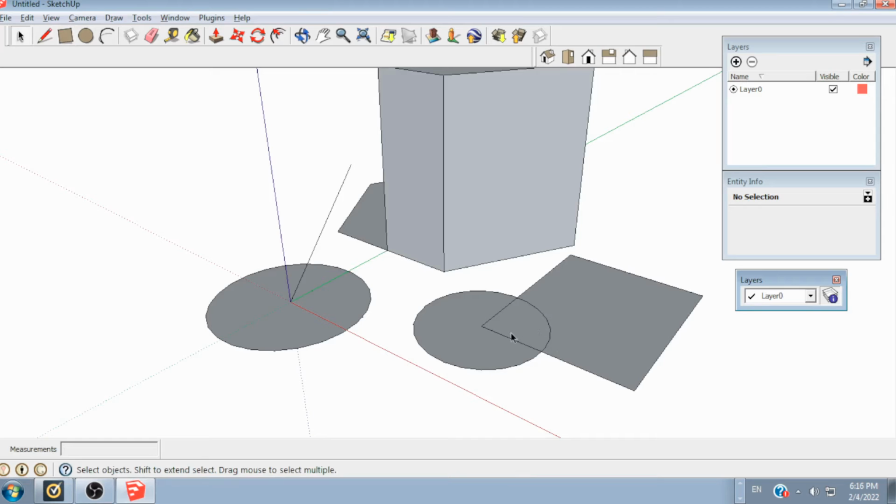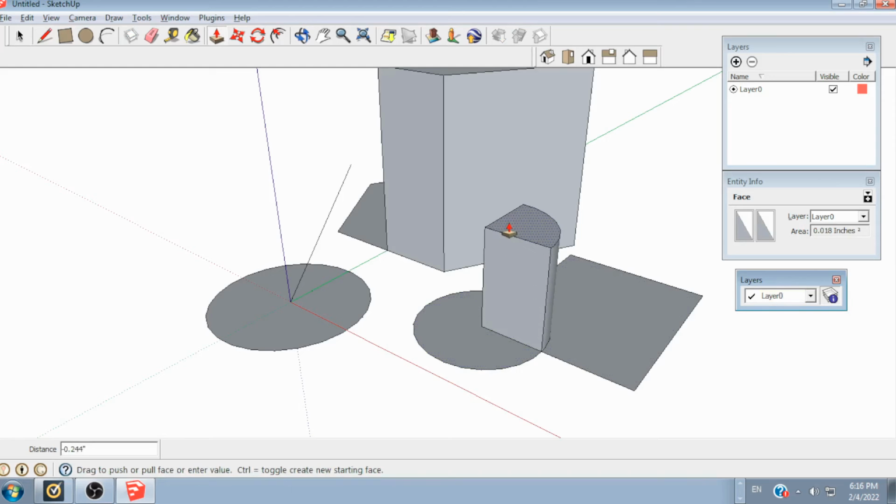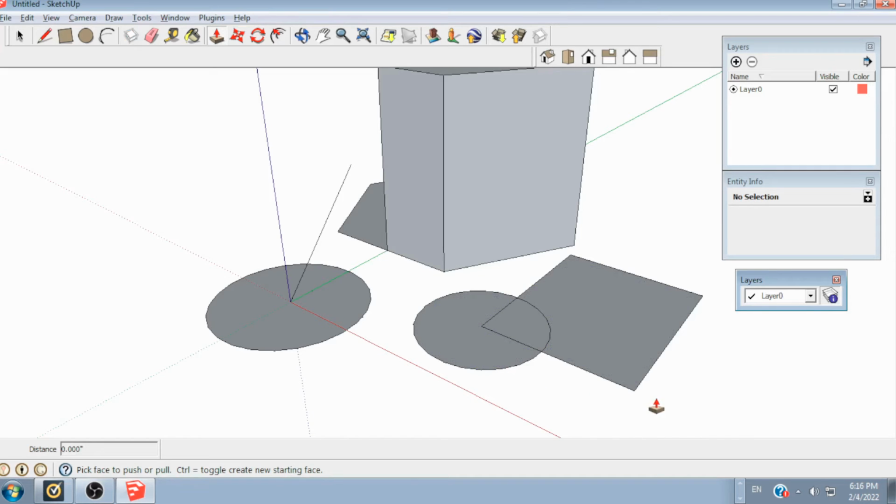And here's a good time to point out that this is a sticky system. So I have 3 surfaces really. If I click this, you can see this shading is this part, the intersection is another section, this is another section. So I click on this and hit P and extrude it. Control Z to wipe that out. And this is